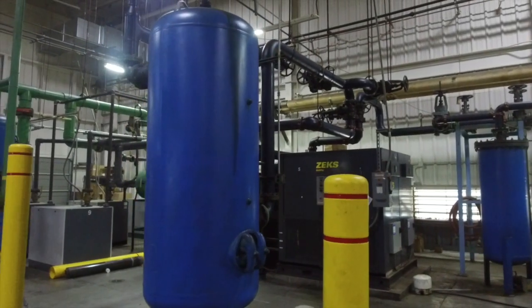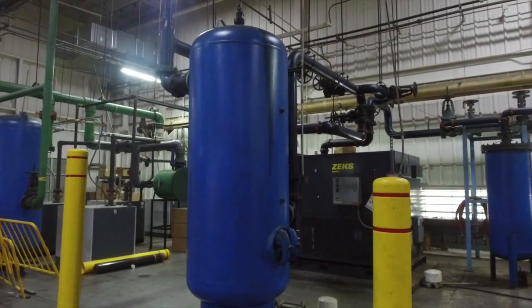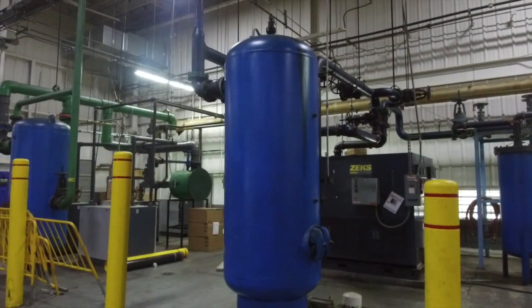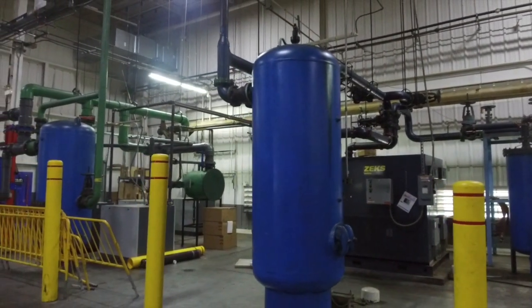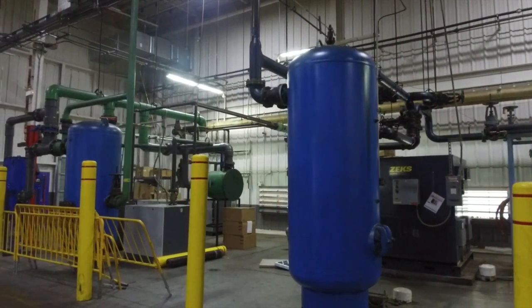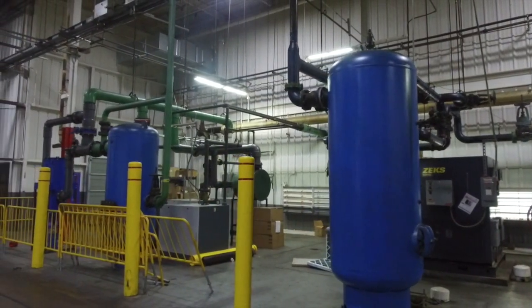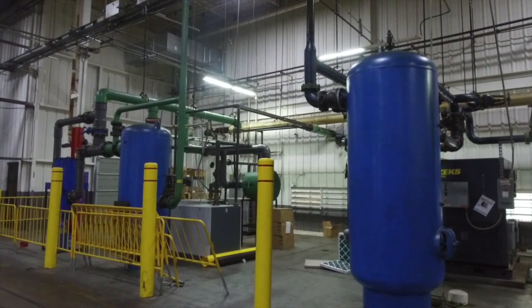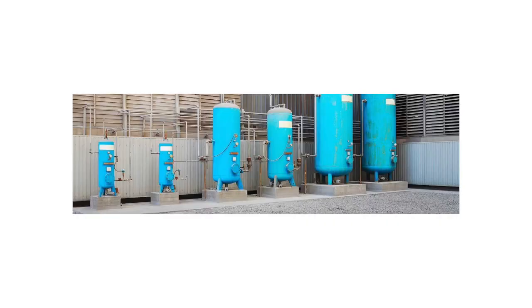Another common device you're going to see on the end-use side of a compressed air system is a surge tank, also called a receiver tank. The primary purpose of a receiver tank is to be a buffer or a smoother. Receivers store compressed air to help keep the pressure constant at times of peak demand. Without a receiver tank, cyclic changes in pressure can alter the performance of actuators and other tools. These tanks are upright and big, and usually many of them are used in series to produce a variety of pressure levels. This picture shows 6 receiver tanks of various sizes.